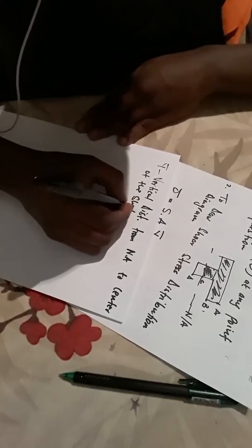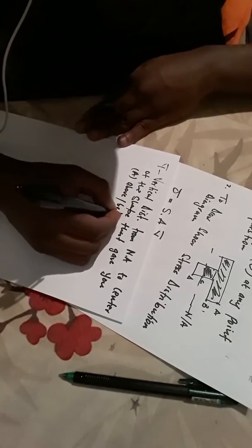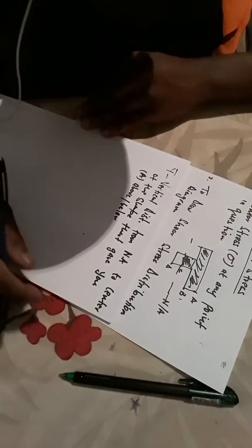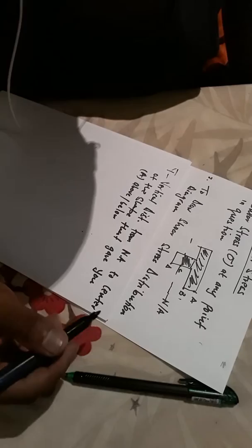to the center of the shape that gave you the area above or below point in question. So when you say y dash bar is the vertical distance from neutral axis to the center of the shape that gave you area below or above point of contact, we say, let's say you are